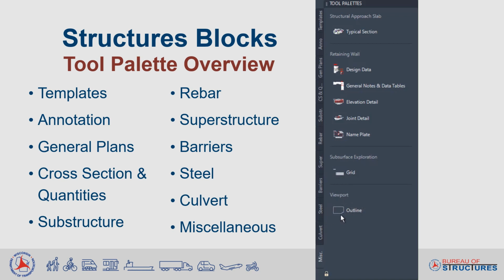And last, there is this viewport block. So this shows the usable outline inside of our sheet border. So if you want to draw a viewport, a single viewport for the entire drawing, that can be useful to show the borders in model space, and then just size the viewport in your layout to that outline.